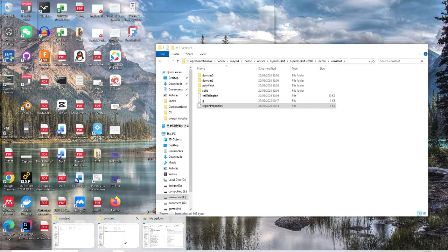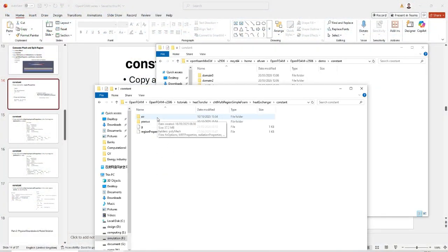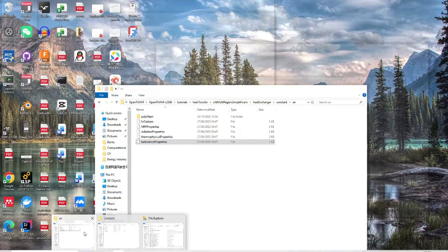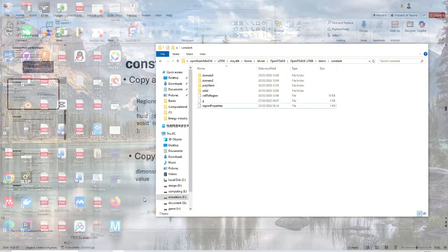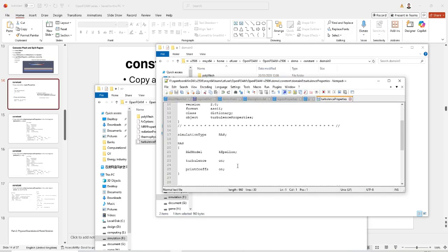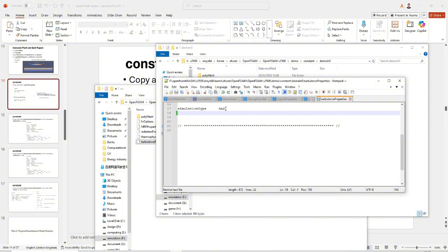Then we now need to check if we have any fluids in the example. So we have. We only need the turbulence properties to be defined for the fluid domains, domain 0 and domain 2. So we copy here, and we have a quick check. This is not laminar, because it uses a turbulence flow with K epsilon, but we want a